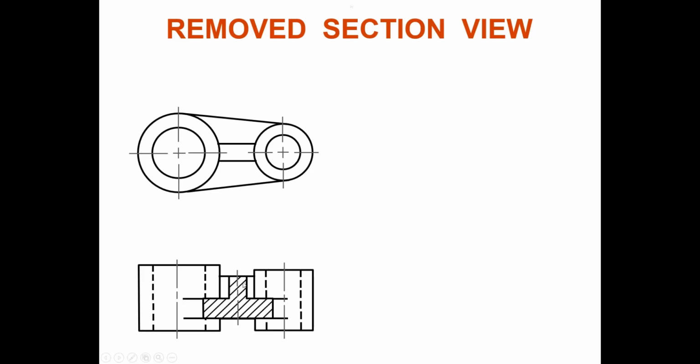But you don't have enough space here to put your inverted T shape. Nampak tak? So that's why, what I show you is revolve section, not remove section. This is what we call revolve section: we cut and rotate at the same position. Clear? Faham kelas?